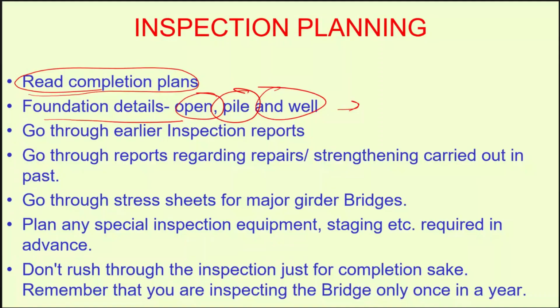Normally there are no chances of the stress sheet being wrong because it has been done meticulously at different levels of care. So if the bridge or a component is misbehaving, that means something wrong has happened between the last inspection and this inspection, and accordingly you need to probe into that, find out the root cause, do the root cause analysis, and then take the mitigating action.